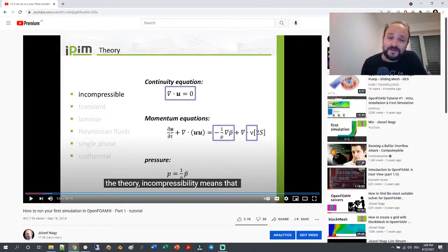So in the Navier-Stokes equations, here you would have rho times U, and also here you would have rho. But since we assume an incompressible flow, which means that the density is constant, you can divide by the density. But in the pressure gradient term, there is no density in the original Navier-Stokes equations. So you do have there 1 divided by rho, and OpenFOAM combines the pressure with this density into one variable, which is the p. But don't forget that, especially if your density is very high and not around 1, then you have to multiply your p-value during post-processing in order to get the correct pressure in Pascal.